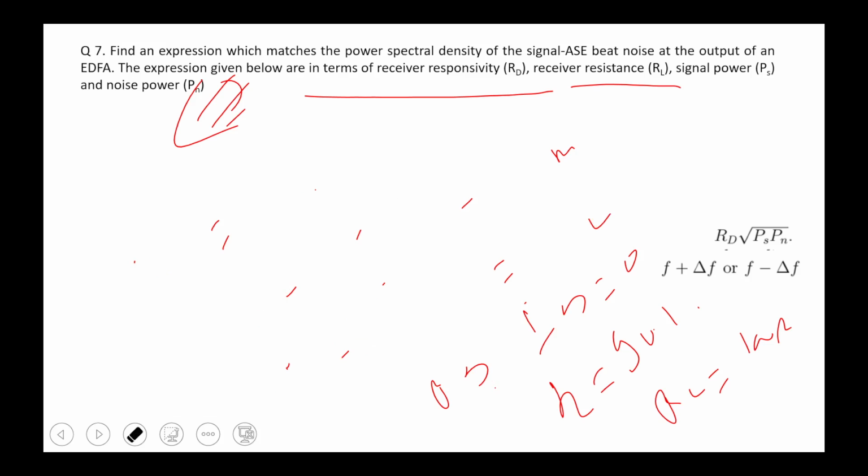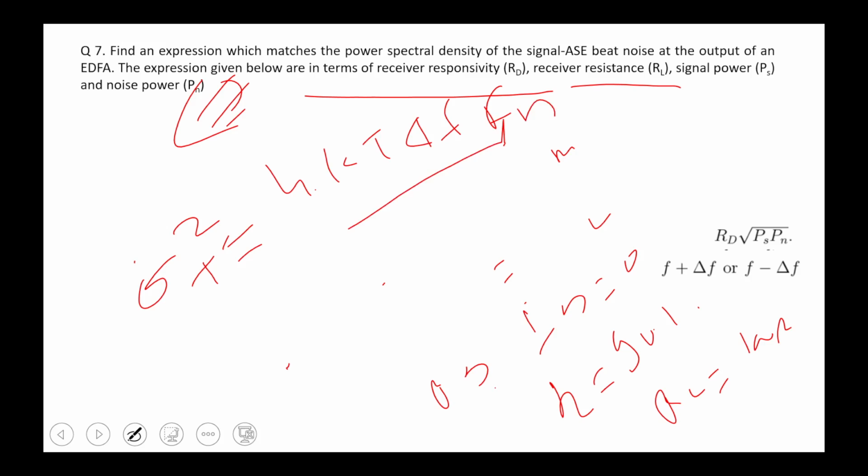You have to calculate how the thermal noise will be calculated. Week 7, I already explained that formula there. The sigma T thermal noise variance will be given equal to 4 kT delta f Fn upon RL. So k is the Boltzmann's constant, T is the temperature, room temperature, delta f is the bandwidth you have to be given. Fn is the noise figure, and RL you have to be given in the questions.